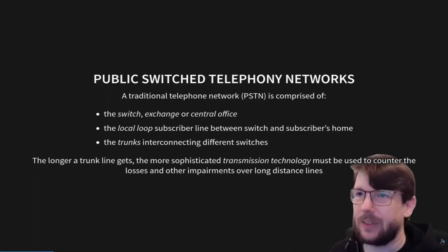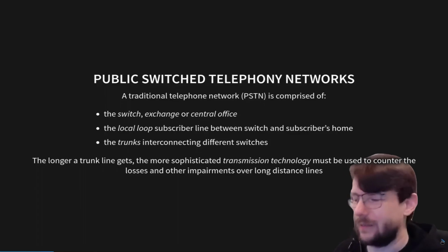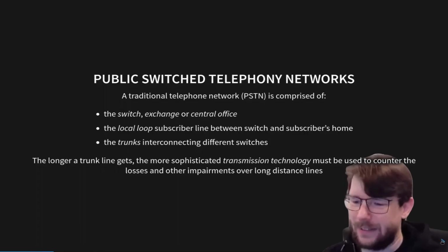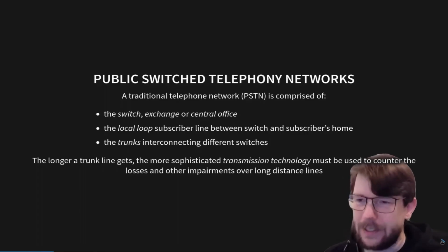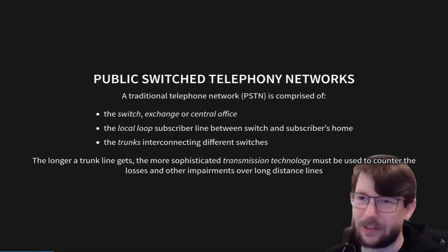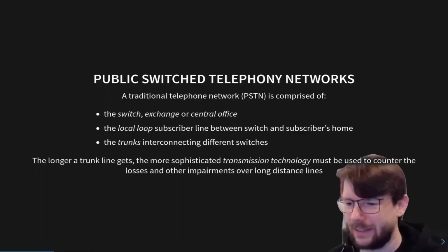But if you use those same wires that you use for the local loop, then we have transmission problems with attenuation and noise in the line, and you need to do amplification, and then you also amplify the noise, and the quality gets worse, and you have crosstalk between different lines, and so on.